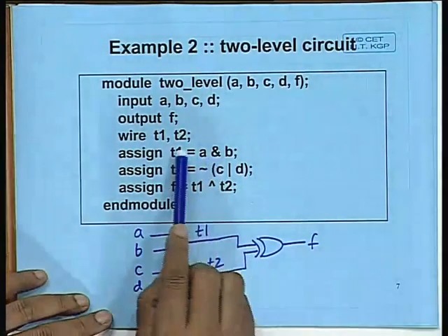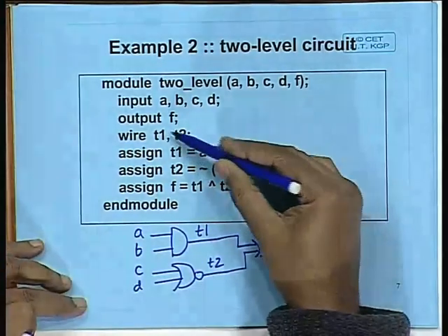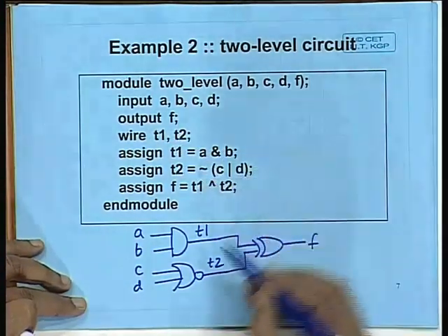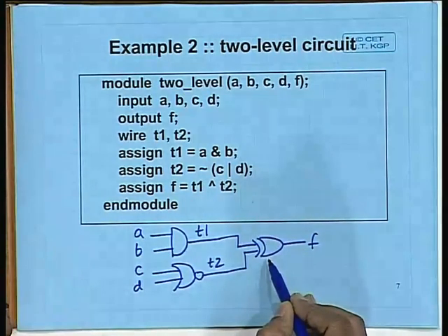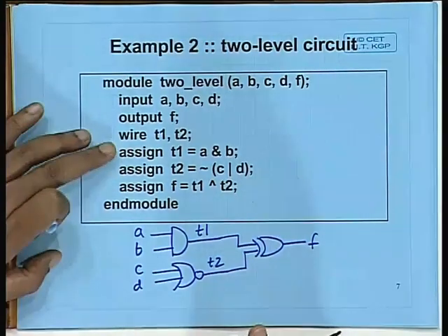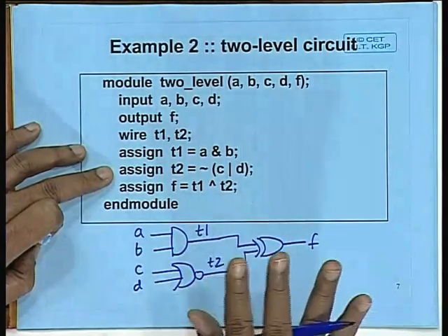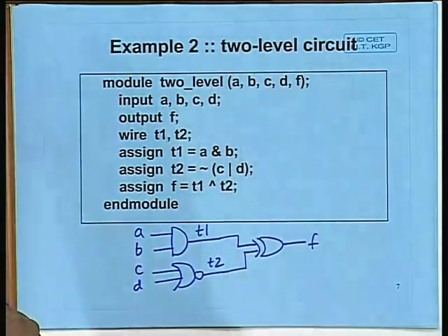So depending on the intermediate wires we use, here we are specifying a 2-level logic. Well, there are some problems that can occur during simulation, which we will see a little later. If you are not very careful about it, then our simulation results and the actual synthesis results may differ, even in the case of simple gates like this.